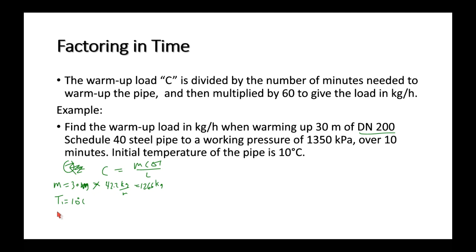It's given to us as 10 degrees Celsius. T2 will be, well, we're going to do 1350 kPa absolute. So 1350 kPa absolute, what does that give us in terms of T2? Does somebody have the steam tables handy? And if you're doing that, you can also figure out the value for L. So find hFG at 1350 and the saturation temperature at 1350, please. Somebody, I don't have my handbook handy.